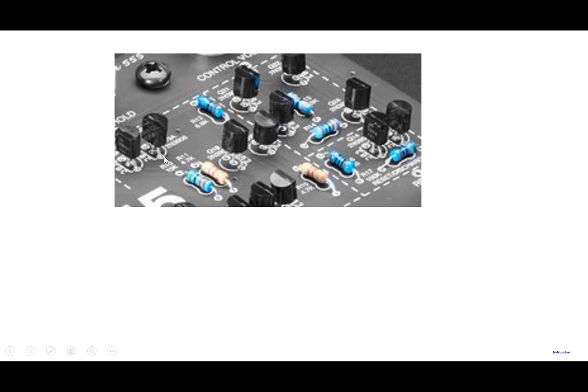Underneath the board there are wires which will connect this transistor to this resistor, or this transistor to this transistor here. The wires were made by depositing metal on the board, and that's why this is called a printed circuit board. The nature of fabrication of circuits was that each of these elements that you see here, a transistor or a resistor, existed as a separate discrete component, and you would pick it up, place it at a certain point, and solder it, right?